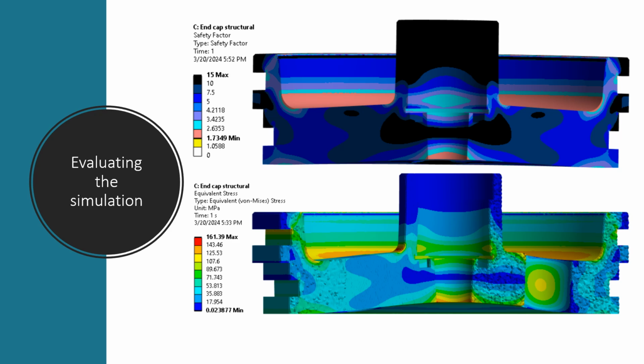These memories are stored in your RAM, and the problem is when your mesh gets really high in element number. The element number means how many elements you have. A problem comes to us that the RAM starts to get full.